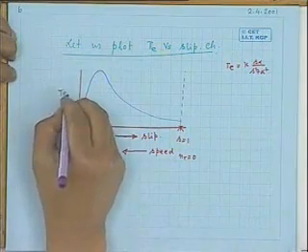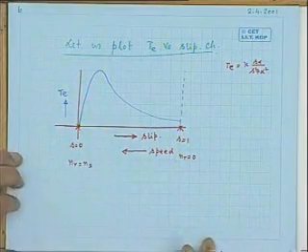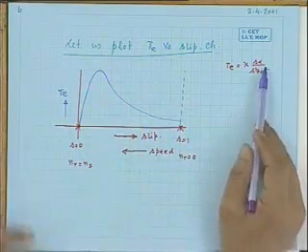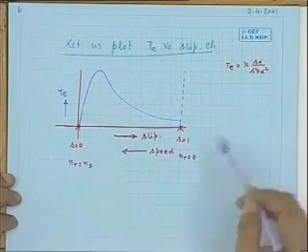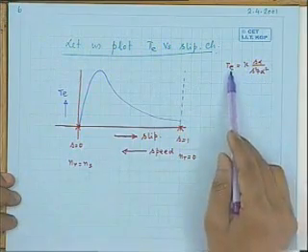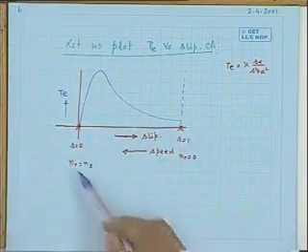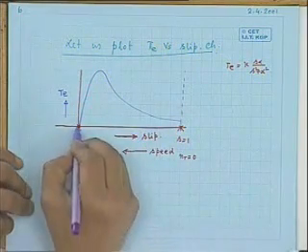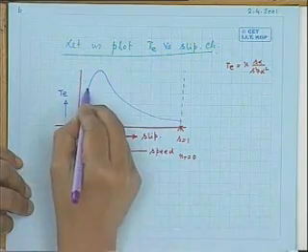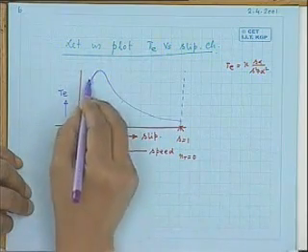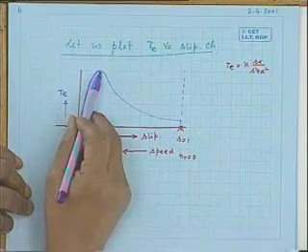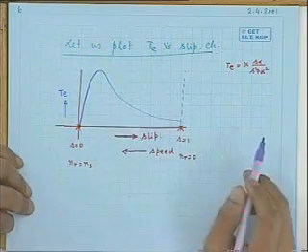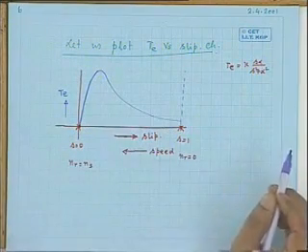This axis is the torque axis. Electromagnetic torque developed by the machine will be varying like this. That is, alpha is known, K is known. You go on varying s and calculate T and plot them. A typical curve will be like this. You will find this initial portion of this curve is more or less like a straight line, and at higher values of slip, it is like a rectangular hyperbola.